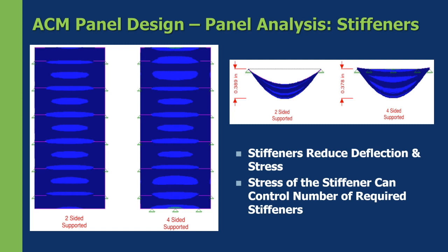So essentially, you adhere the stiffeners to the panel, and over time you will see from the exterior of the building little areas where the stiffeners are. That's called the oil canning effect. And sometimes you can have that conversation with the architect and say, my engineer's done everything, stiffeners are still required, and I just want to let you know because oil canning could happen down the road.